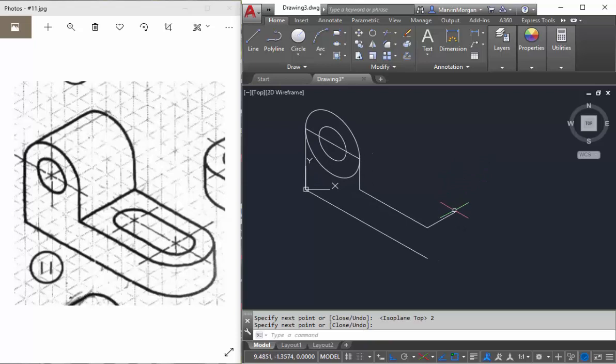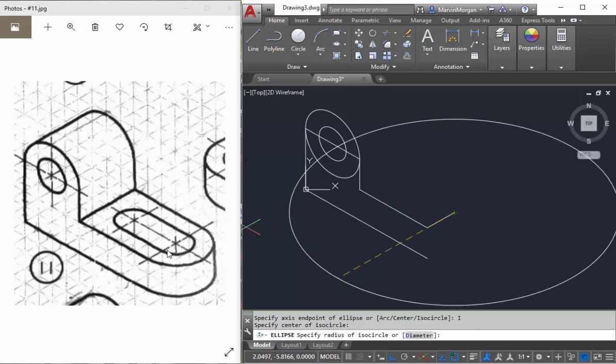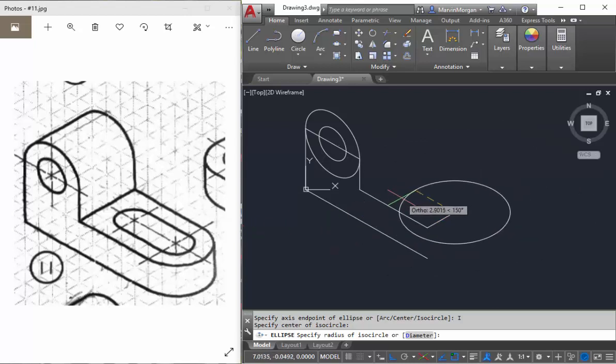Now that I have that established, I can go ahead and prepare the circles here, or the arches. Going back to the axis end, choose ISO circle. I click the end of the line. That's my center point. Coming out, as you can see in the picture, my radius will be considered 1 square. So I'll type in 1.